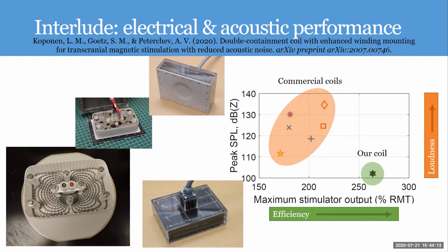I see. And I guess nothing, or very few things in that, are very good at transporting heat. The corundum is better at transporting heat than most metals. So the corundum filled epoxy, when it's filled to the sagging point, actually acts as a very good heat sink.